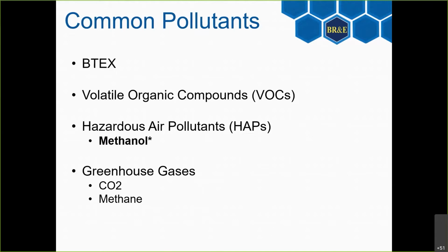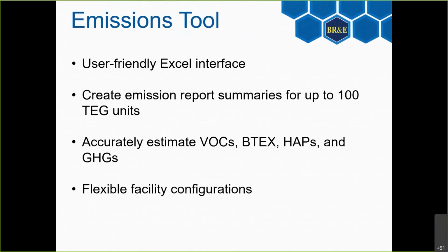An important note there is we have talked with some state agencies, and we've got good relationships with many of the state agencies who do these kinds of emissions reviews. Some of them have let me know that they are becoming a bit more strict on tracking methanol emissions at all sites, not even just dehy sites, but that's where it can be commonly found. Having a tool that can accurately estimate that is very, very important. Another thing that you'll see we summarize in our report are the greenhouse gases, your carbon dioxide and methane, and we'll come up with what you hear called a CO2 equivalent in our template. So the emissions tool was really created to help people who are less familiar with modeling TEG units in ProMax.